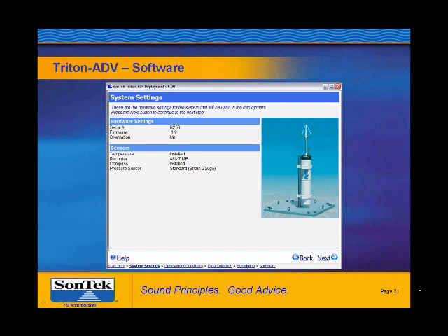So typically for tides, what we're using is an average value over the course of the velocity sampling time. So we would average the pressure value over the course of, say, 60 to 100 to 120 seconds, and that will filter out all of the waves and give you a mean water level elevation. And then once you combine that with subsequent measurements, then you can very clearly start picking out the tide. So it really comes down to how often we sample and how much of that data we average.